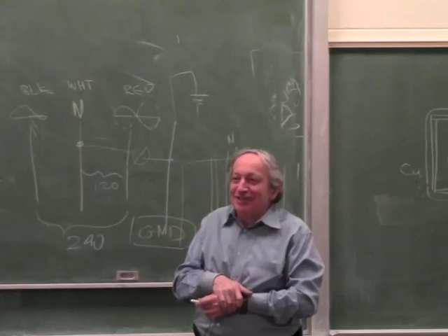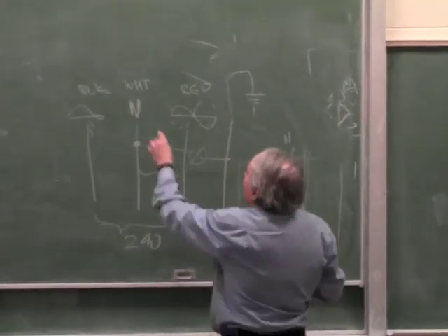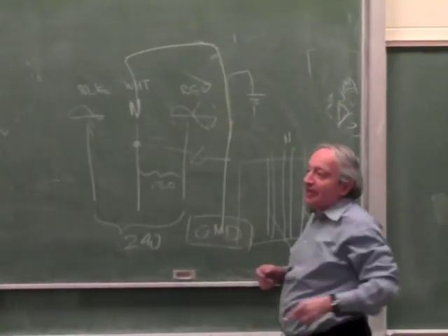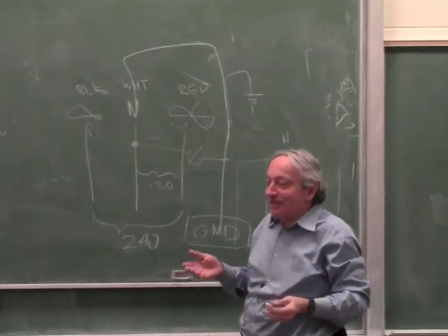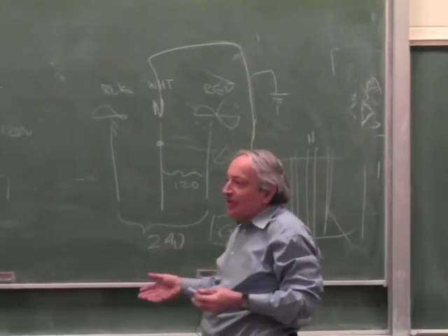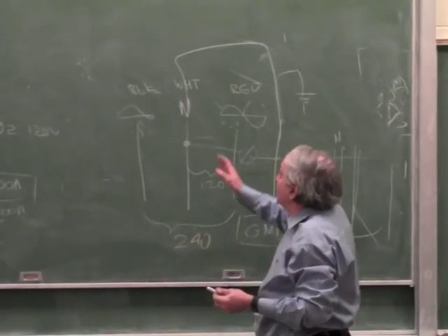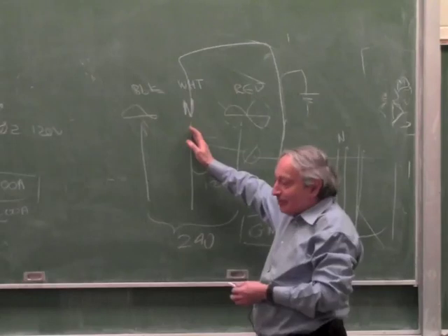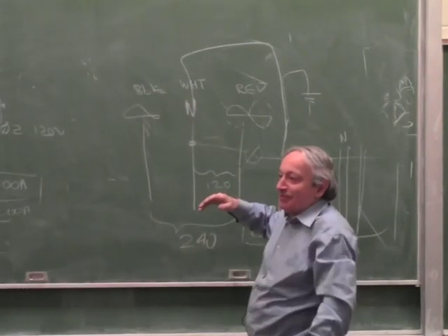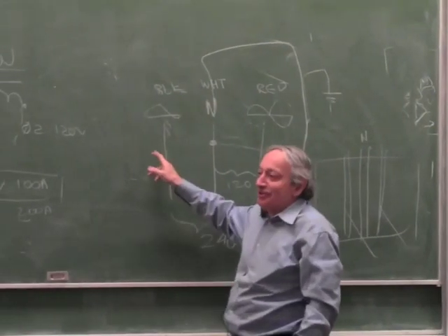It's the same story every year. Of course it's short. The neutral and ground are connected together. It's one wire outside the house. And if you ever try it, you'll see. You can try it with power on, because neutral doesn't have any power. But just to be safe, don't try it with power on, in case you plug in the ohmmeter at the wrong place.